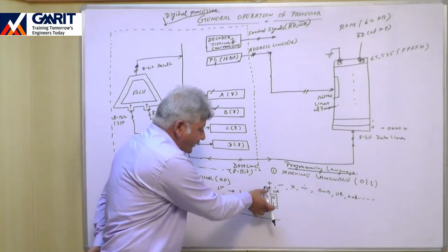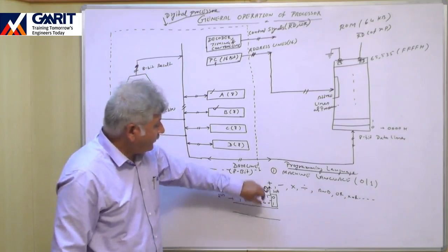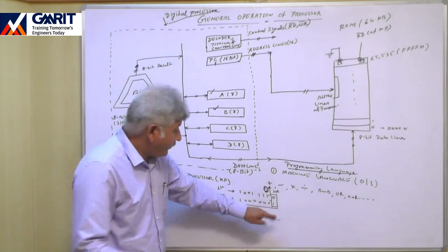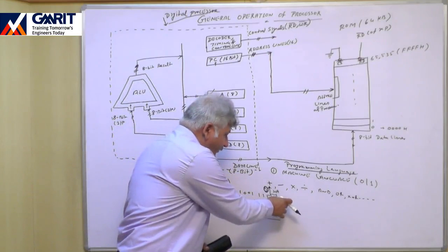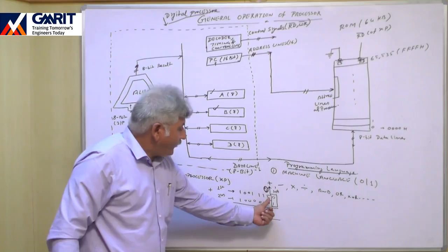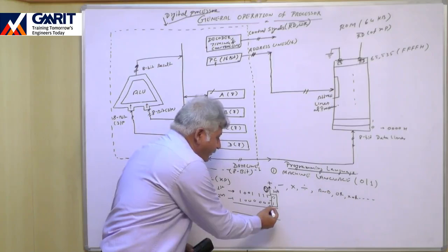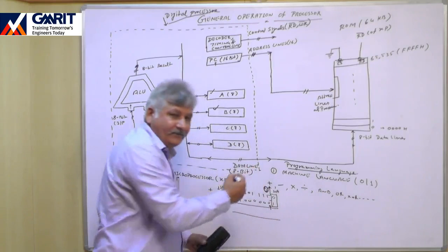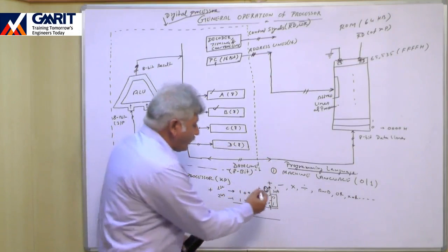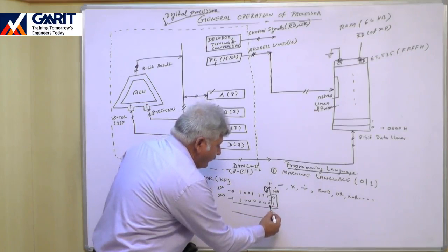So when you are adding the next two bits, at that time there may be a possibility that there may be some carry. In this particular example, 0 plus 1 will not generate any carry. But suppose in place of 0, 1 was there, then 1 plus 1 will be 0 and a carry will be generated. So we cannot use a half adder to add this particular bit, because there may be a possibility of carries. That's why to perform addition over this second bit, you require one full adder.